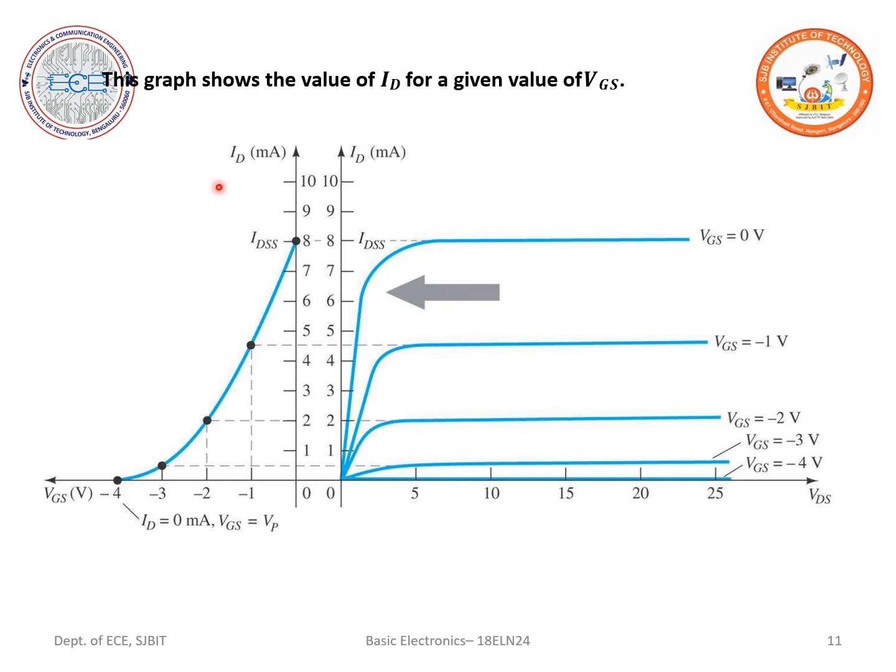Similarly, for the P-channel JFET, you have the same characteristic curves to be plotted. For the transfer characteristic, we plot a graph of ID versus VGS by keeping VDS as constant, where my VGS is now positive. As you make it more positive, the current is going to decrease to 0. Similarly, when we plot a graph of ID versus VDS by keeping VGS as constant, remember that for the P-channel JFET, VGS is always a positive value.